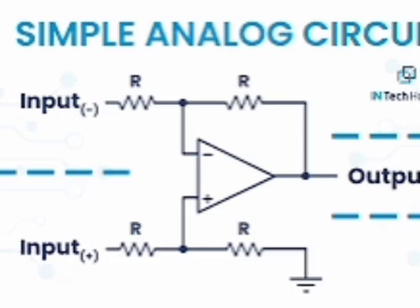Small signal amplifier analysis. For large value microfarad capacitors: medium frequency short circuit, low frequency active, high frequency short circuit. For small value picofarad capacitors: medium frequency open circuit, low frequency open circuit, high frequency active.